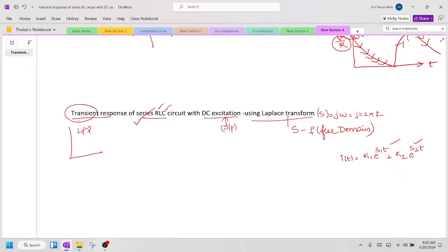For example, you have turned on a fan. This is nothing but the current in the fan, and this is nothing but the time. Just as you turn on the fan, it takes some time. It oscillates and tries to reach the required speed of 1500 rpm. As soon as you turn on the fan, it starts moving from 100 rpm to 300, 400, 1000, 1200, 1300, and it reaches the required speed. What is the time taken by the fan to reach its speed? It's only 4 seconds, or approximately 4 times the time constant.